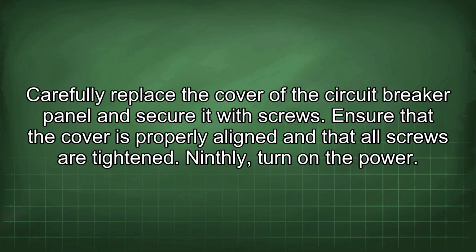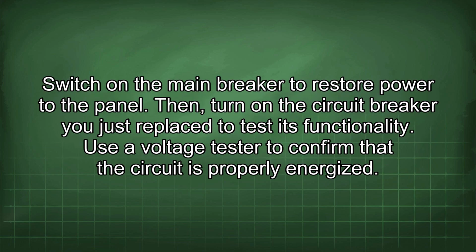Ninthly, turn on the power. Switch on the main breaker to restore power to the panel. Then turn on the circuit breaker you just replaced to test its functionality. Use a voltage tester to confirm that the circuit is properly energized.